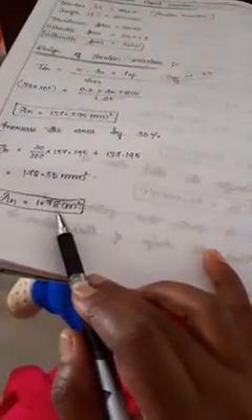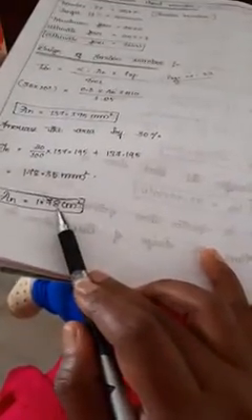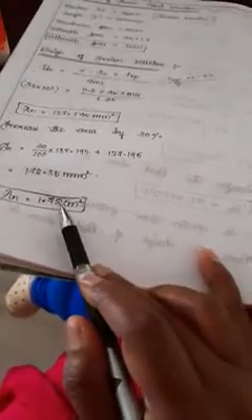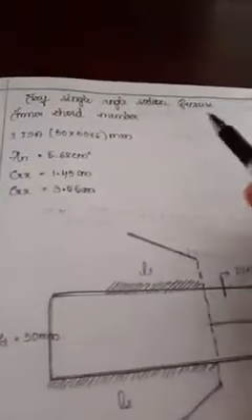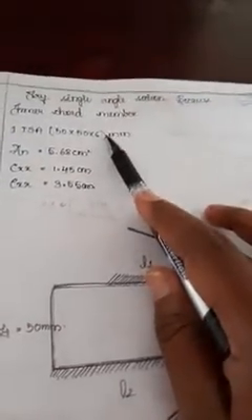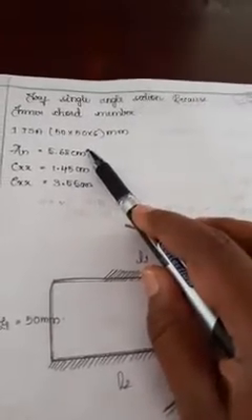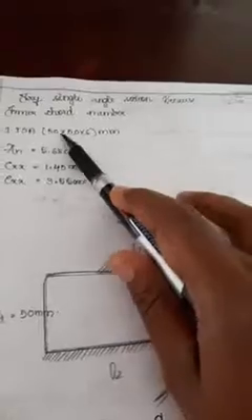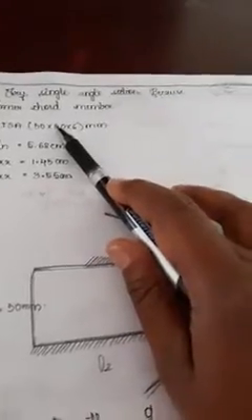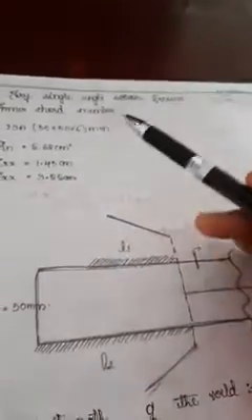So when you select your angle, the area of that angle should be near to this value or greater. It can also be greater than that. When you select your angle, you have selected this angle, 50 by 50 by 6 mm, right? In that, from the steel table, take the area for this particular angle. Sometimes it is better to choose greater than that.